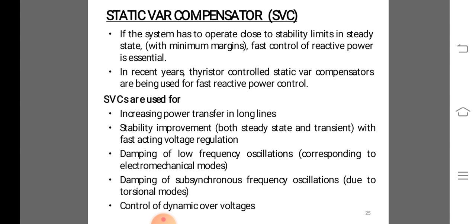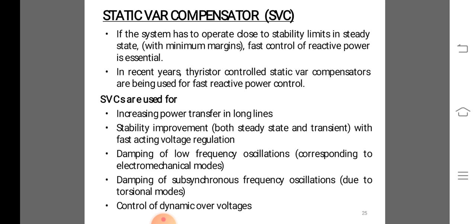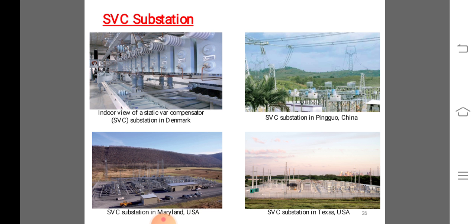The secondary reactor is normally non-existent, as it is more economical to design the reactor transformer with 200% leakage impedance between primary and secondary windings. The delta connected tertiary winding will effectively compensate the triple harmonic.